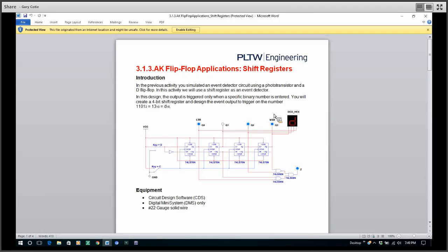So if we take a look at it, here's the most significant bit, and in here, the least significant bit. We're shifting the data into this flip-flop, which is the least significant bit. There's our data coming in. Here's our clock. This particular clock is a falling edge because we have the little not symbol, or active low symbol, on there. As we shift the pattern in and make a D, which is 1, 1, 0, 1, down here we detect that D is in the shift register. So this is a detection circuit, an event detector. It's detecting the event of a D loaded into the 4 registers, or the 4 flip-flops.